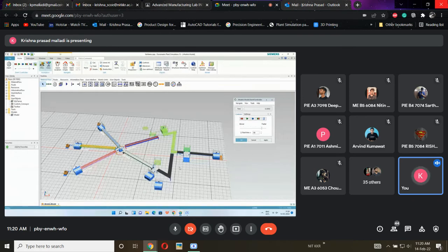After using these four buffers, I can run the simulation for 2 hours. After that, again, it will be in blocking phase. So after utilizing these buffers, I will be getting more than 1 hour 45 minutes extra. That will be an advantage. If this is a continuous running plant, now I can propose some layouts. This is not a feasible layout for running this type of production, so you can increase the machinery or the length of the conveyor, or you need to do some improvements so that your rate of production won't be affected by these parts.